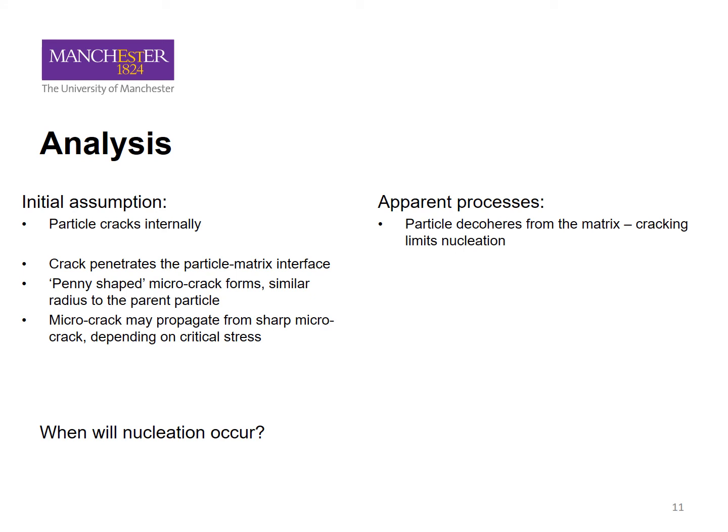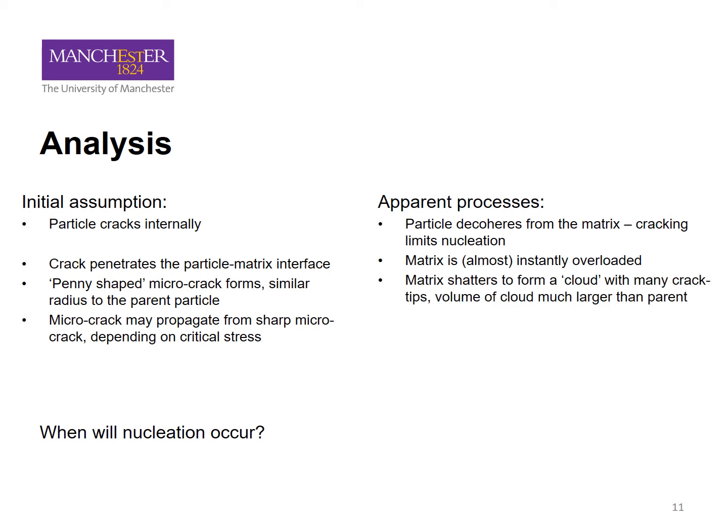A particle decoheres from the matrix. Cracking isn't essential; if anything, it limits nucleation. The matrix is then almost instantly overloaded. The particles themselves are elastic brittle particles surrounded by a matrix that at high levels of strain is almost perfectly plastic. So they have far higher strain energies and are bearing a significant fraction of the stress. So if they decohere from the matrix and shed all of that load, then the surrounding matrix appears to shatter to form a cloud with many crack tips, and the volume of the cloud is much larger than that of the parent. We didn't observe any microcrack propagation